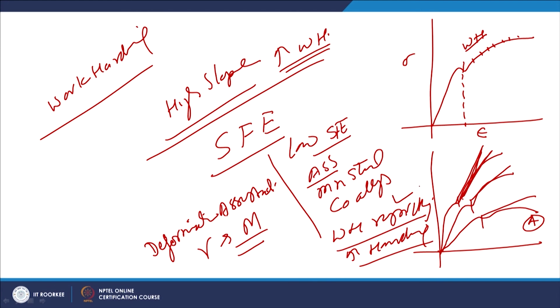This combination of rapid work hardening and deformation assisted transformation leads to improvement in the hardness and wear resistance of low SFE materials, especially austenitic stainless steel and manganese steels. In other cases like cobalt alloys, austenite to martensitic transformation will of course not be applicable, but these low SFE materials will experience a much higher work hardening rate, leading to improvement in hardness and wear resistance of the material.